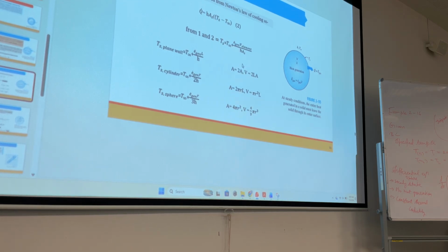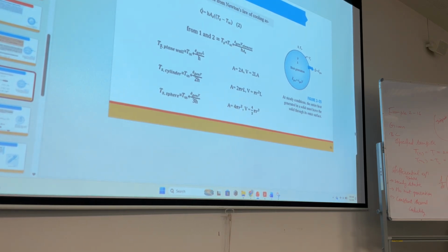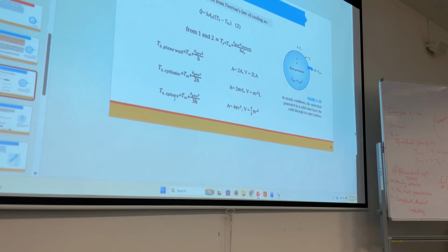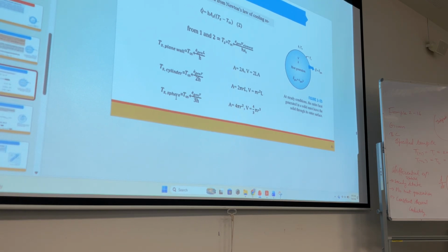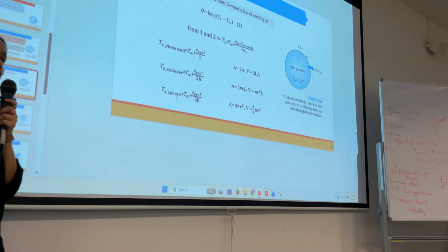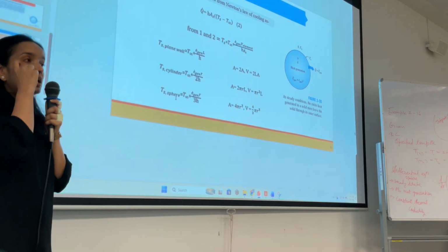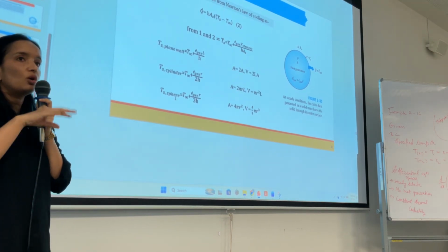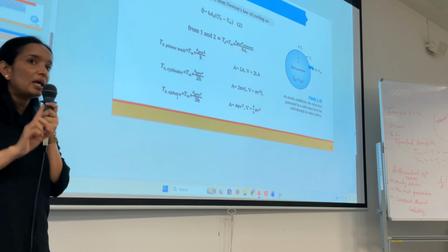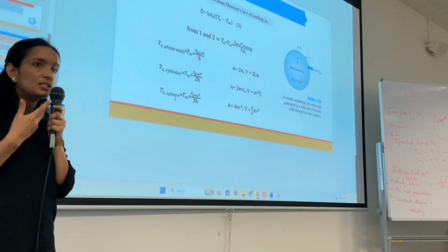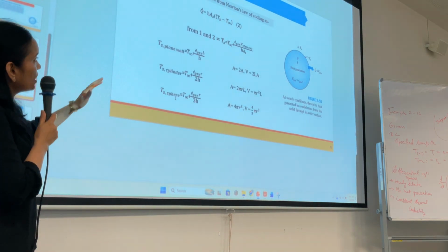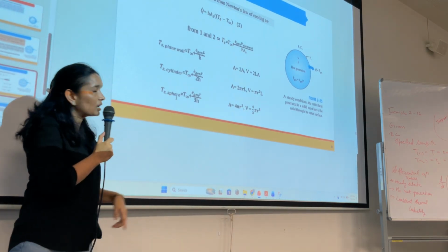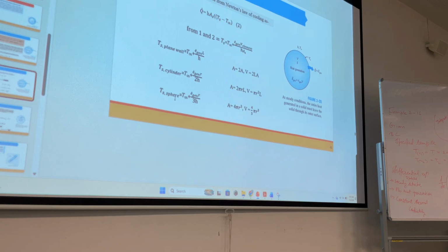What is this equation saying? From this equation you can find out the surface temperature of a plane wall, of a cylinder, of a sphere. If the heat is generated inside that object, the heat will be lost outside by convection. If you want to know the surface temperature of that object, of a plane wall, of a sphere, of a cylinder, in a case when there is a heat generation inside it, you can find out like this, with these equations. You just input the area and volume for each shape and you will get this.